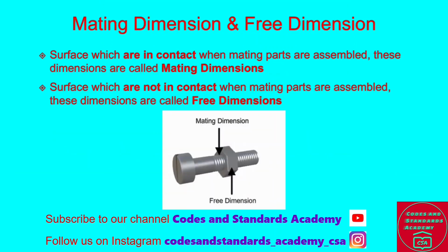Before going to the topic, let's learn a few types of dimensions and sizes. Firstly, mating dimension. Surfaces which are in contact when mating parts are assembled, those are called mating dimensions. Similarly, surfaces which are not in contact when mating parts are assembled, those dimensions are called free dimensions.